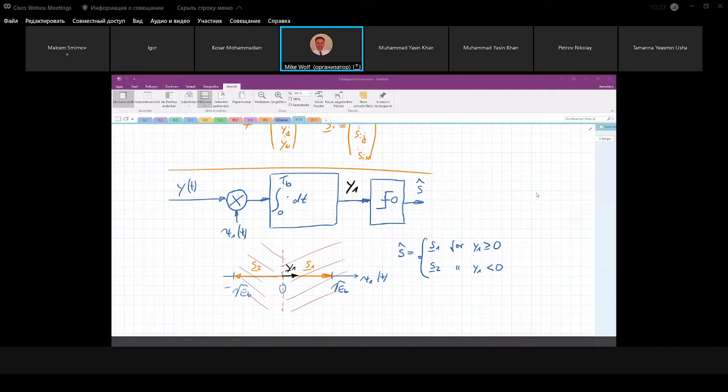Measure the difference energy with two possible transmit signals. So for binary transmission, there are two possible transmit signals for each bit to be represented. And we measure basically the difference energy to the received signal. And then we said at the end, we can map this into our vector notation. Also, the vector is only one-dimensional in this case. And we said we are at the end only interested in the projection of the signal.